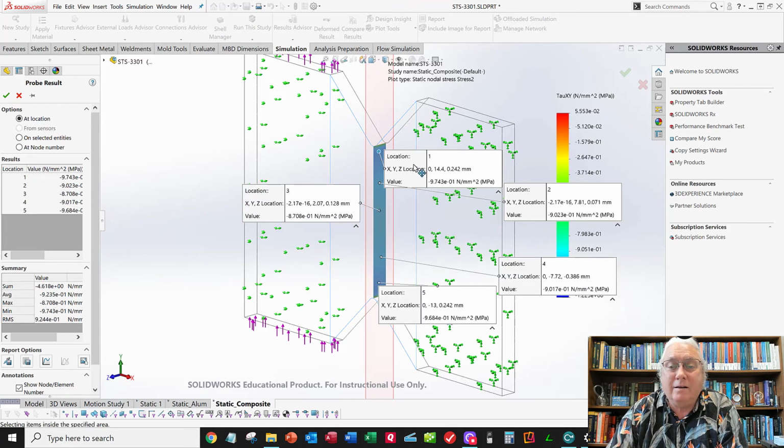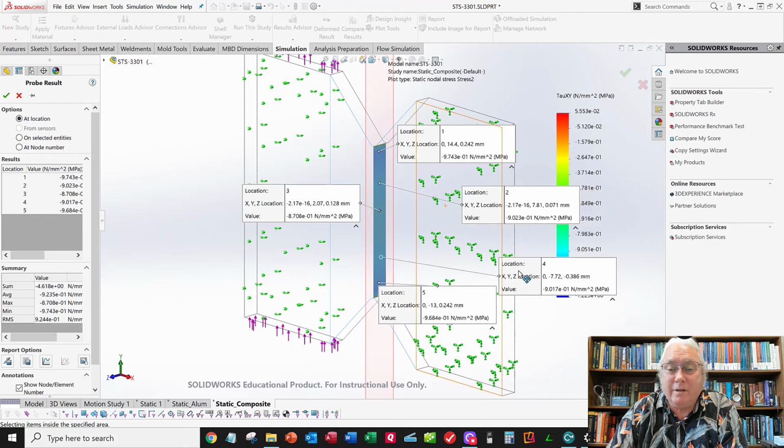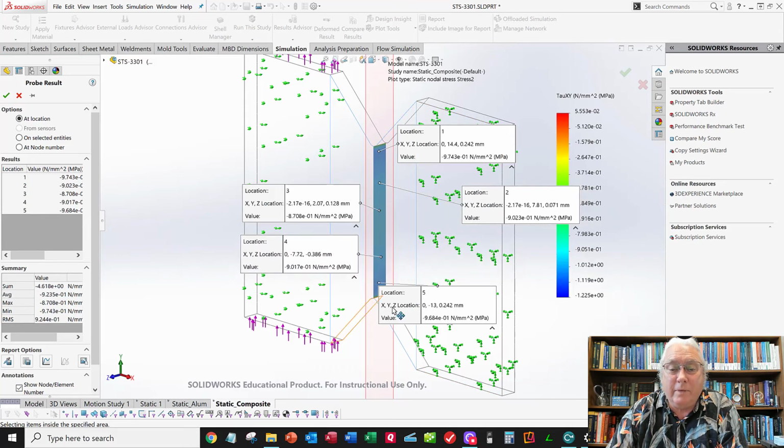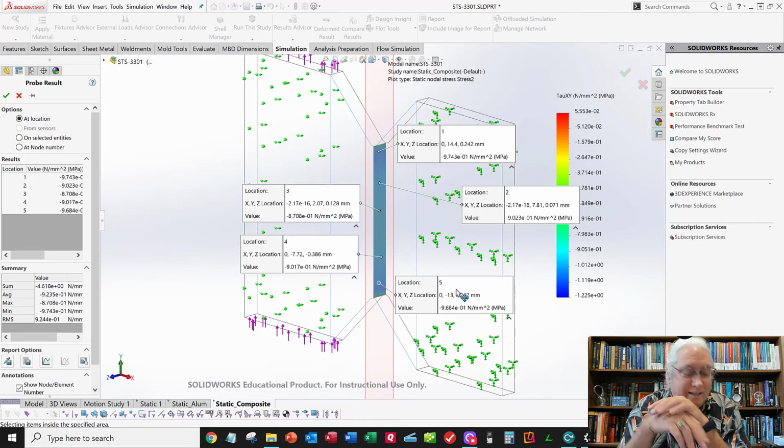So what do you think? How can the stress be the same for the aluminum as it is for this one? Well, think about it. What parameters were in the equations we used? We had areas, we had moments of inertia, we had first area moment of inertia, we had forces. Did you see Young's modulus in any of those equations? Did you see shear modulus? For stresses, it doesn't matter. Stresses are stresses. Doesn't matter what material you have.